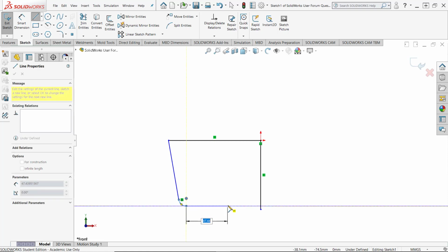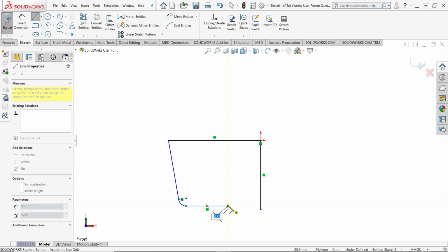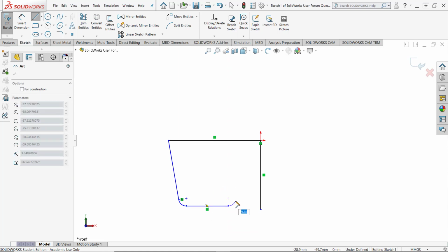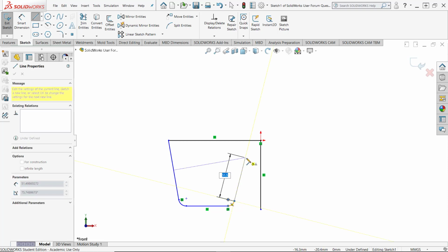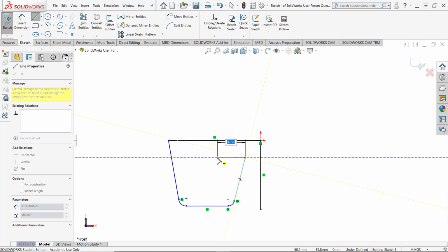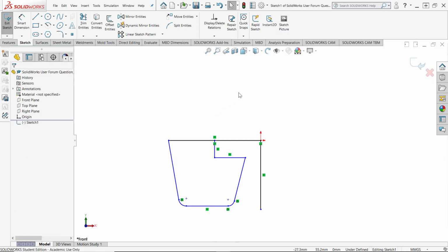And so I'm going to come over here horizontally. Again, I'll move my mouse away, bring it back to the end of the previous line, and it changes into an arc. I'm going to then come up, and come over horizontally. Now I want to track down from the midpoint of that line, so I'll just scrub that point. Don't click on it, just scrub that point, find it,